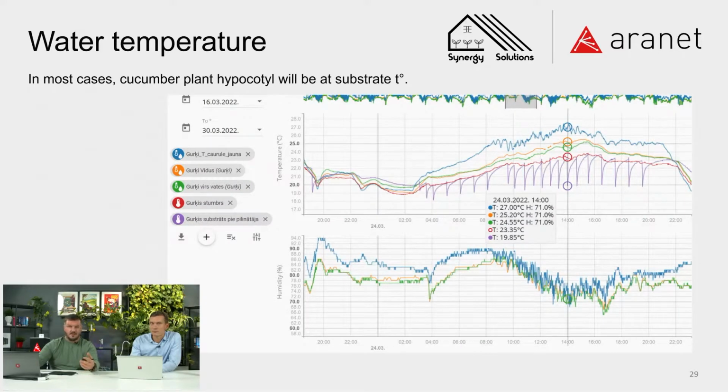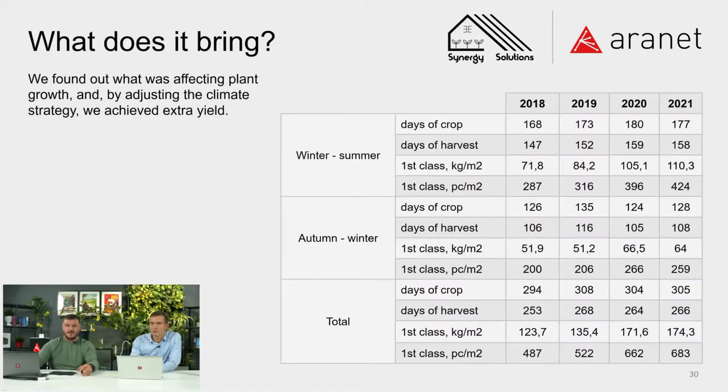And then from that, you know when your plant can get to a dew point, and you can adjust your irrigation temperature. That will give you a lot of valuable lessons just by monitoring the irrigation water temperature, which is easy to do with temperature probe sensors.